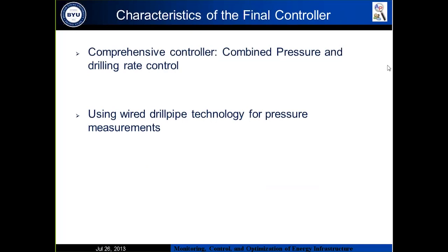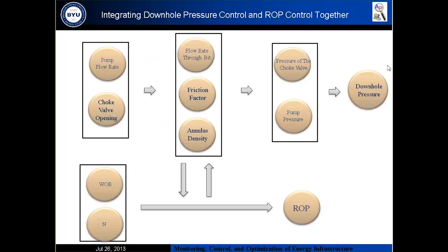So far, I have just had 5 pressure sensors, but I'm looking to add more pressure sensors. As they drill more, the number of pressure sensors will increase to make it more realistic. And then I will use an optimization-based approach, and I will be adding some fault tolerance, like the tolerance for kick, managing the kick, and also stick-slip condition if I have time for it.